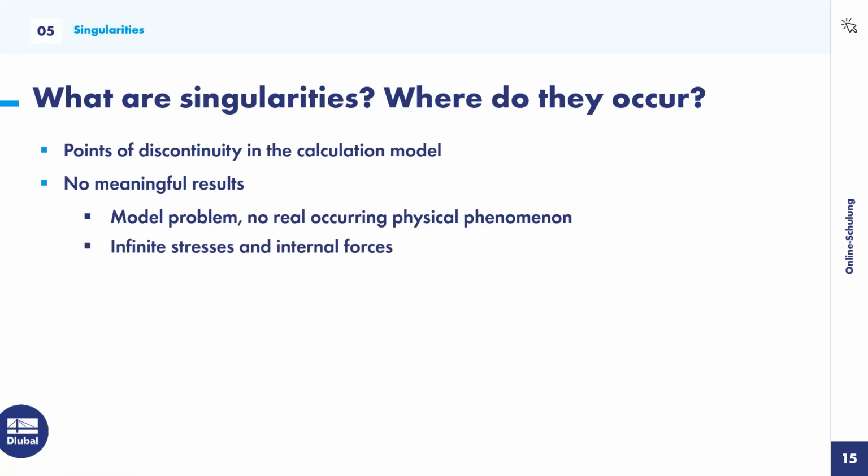We will get infinite stresses and infinite internal forces. A mesh refinement will not improve the result. On the contrary, it most likely will just increase the singularity.